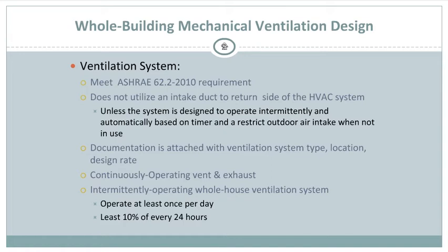If your units are coming in at a HERS rating of 70 just to meet Energy Star, you probably don't have to bring fresh air into the unit. It should be tight enough and it should be breathing enough to where it's okay. But once you get into HERS ratings of 50 and lower, that's when you need to start taking this air exchange into consideration.